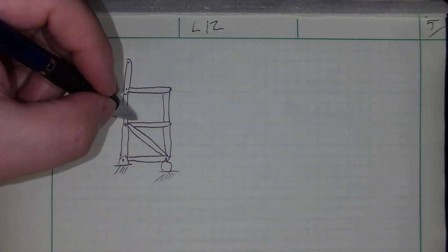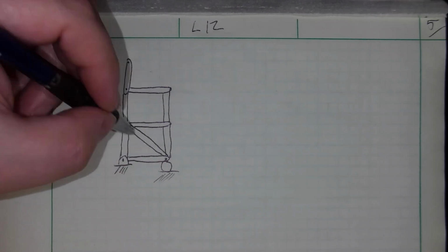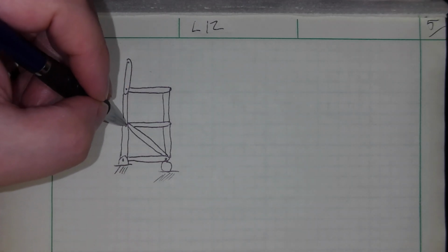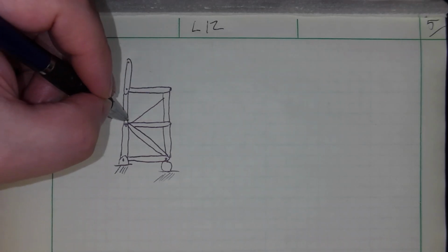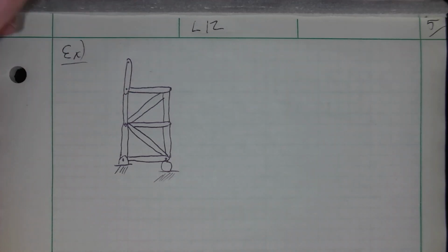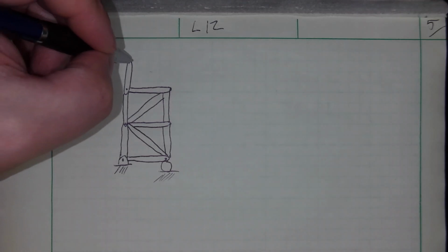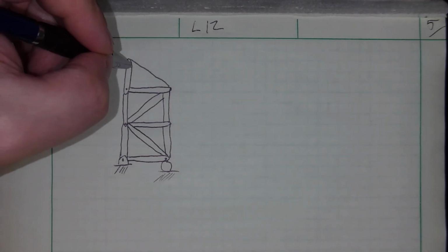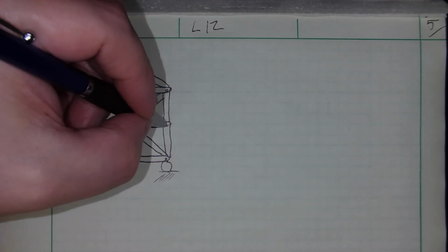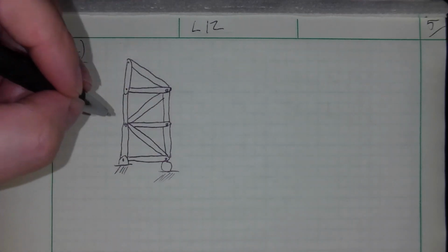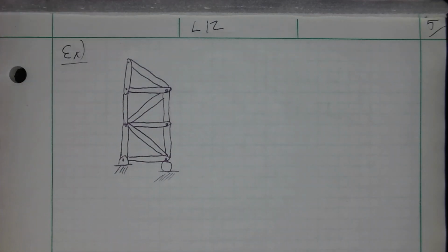And then there's a diagonal here, and you've got another diagonal member right here. I could try to describe it, or I could just draw 2 lines and you can see it. And then finally, we've got to finish this triangle off up here. Again, trusses are a series of triangles because they don't flatten very easily. So pin all of those connections.